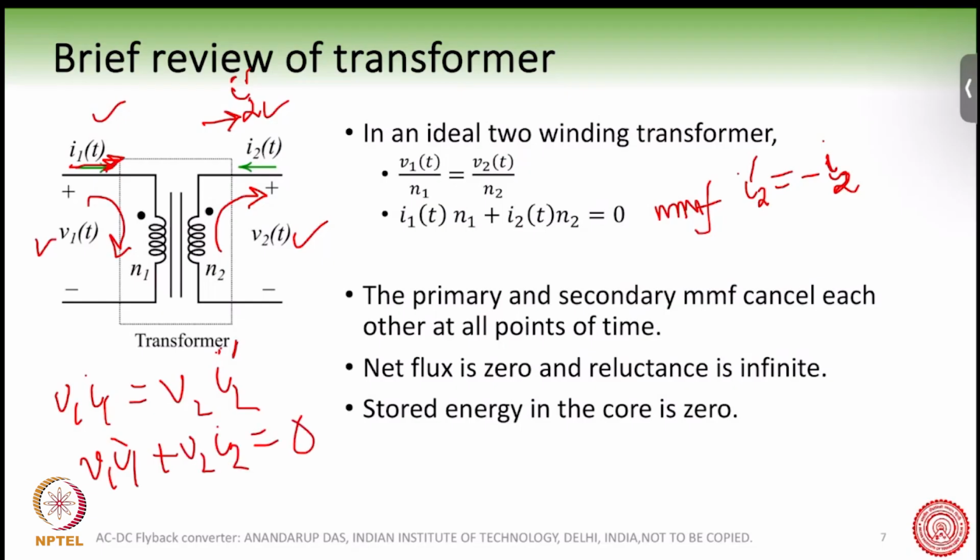But here, in this first equation, I have taken V1 I1 equal to V2 I2 dash. So this comes from the energy point of view, that power in is equal to power out. Whereas in the second equation, V1 I1 plus V2 I2 equal to 0, this comes from the two-port convention, which we are going to use. In two-port convention, you can see here this plus, the current should enter both the ports, right? So we are going to go with that.